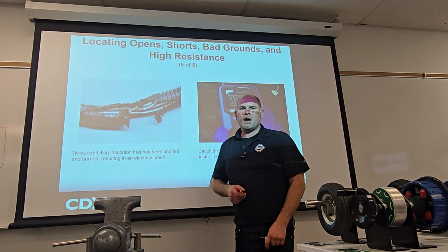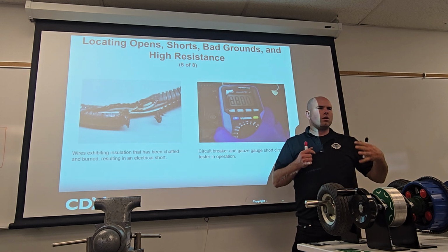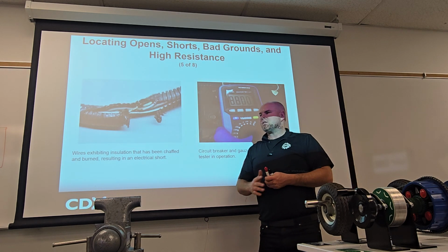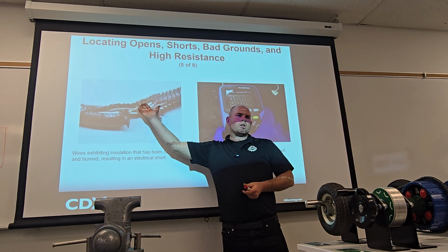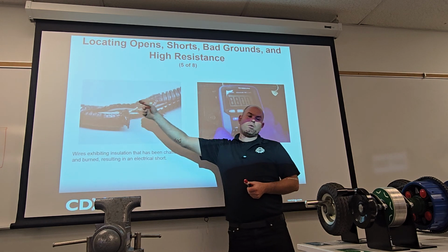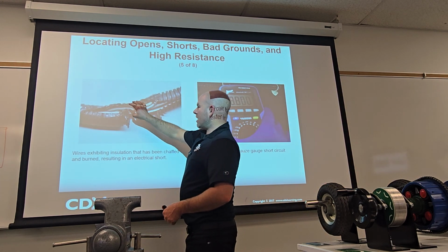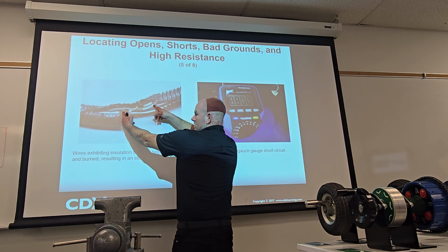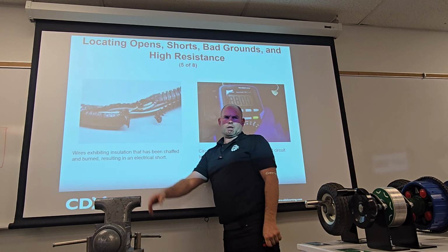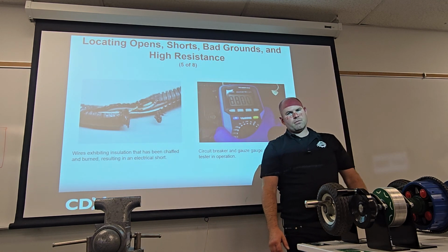So when you go about the circuit, understanding what the symptom is, you're going to kind of know what you're looking for. This one is kind of a bad one, this one causes all sorts of stuff. If this one was just, let's say a mouse chewed it here and there's a 4-inch section missing, that's just an open all the time. That's for sure an open.